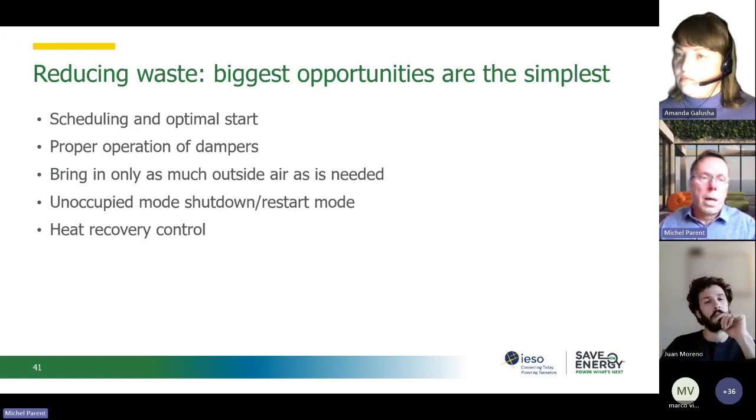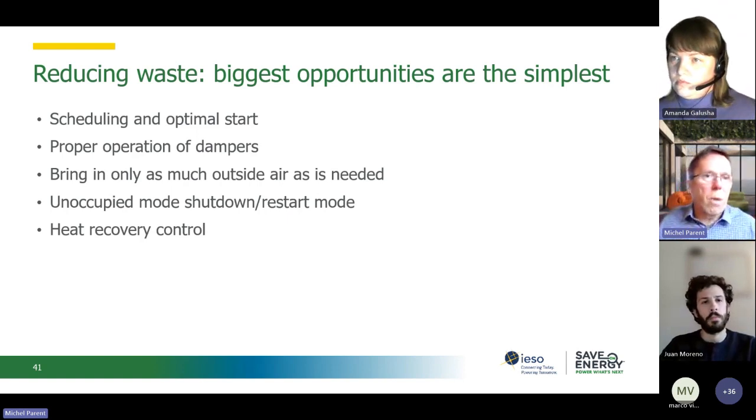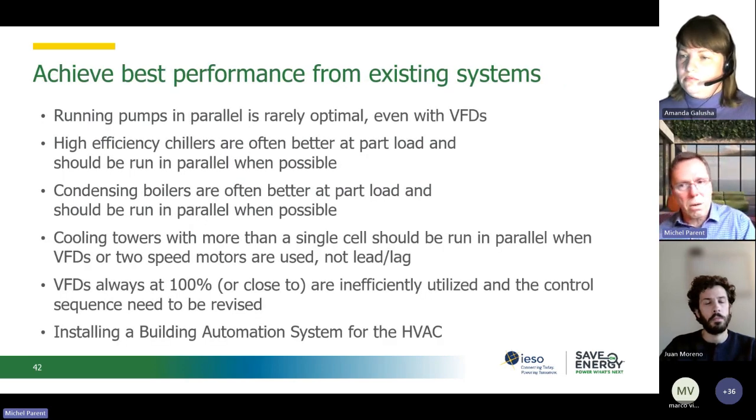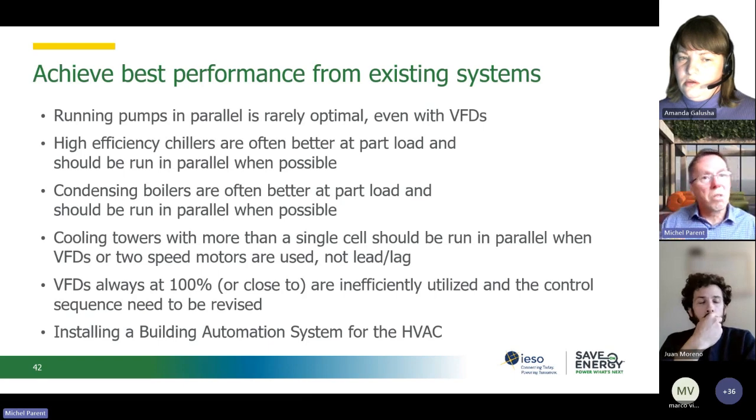So reducing waste in recommissioning, we get 50% of our savings from optimal scheduling. And that doesn't mean just optimal start. It's just by knowing the system and reducing it, doing setback. Some people think setback doesn't save. It doesn't save because in the morning, the system has to catch up. Well, that's a misconception. Setback reduces your load, it will always save. You have to be careful to do it properly so you don't create comfort issues. But if somebody tells you setback doesn't save, that's wrong.